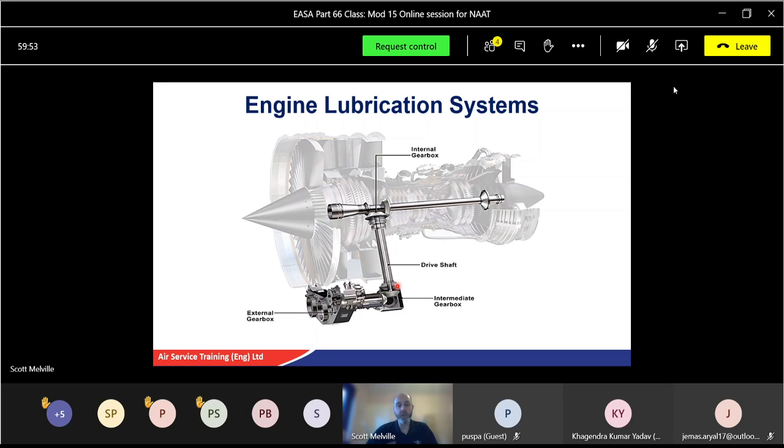The high-pressure spool is the smallest one, and that's the one that spins fastest because it's smaller. And then when the engine starts, the gas will come out of that one, and then go into the IP, and then to the LP in the end as well. So the gas moves it. So it's always the HP one, the smallest shaft. So it's a nice little example to show you. I might use that diagram actually when we do the spools anyway.